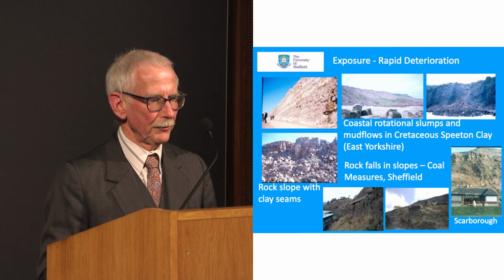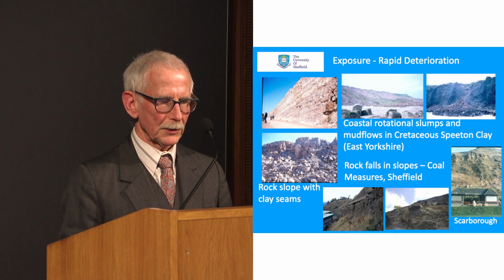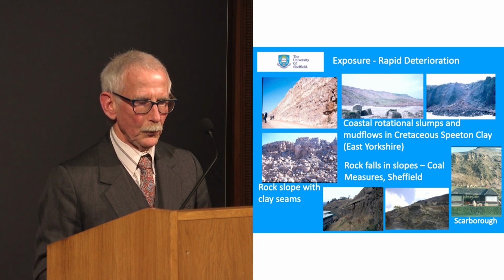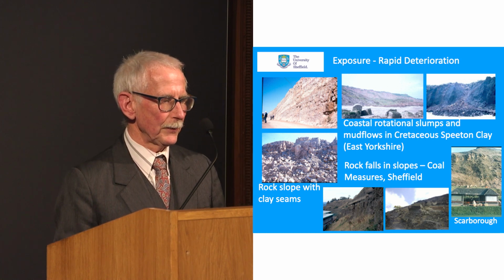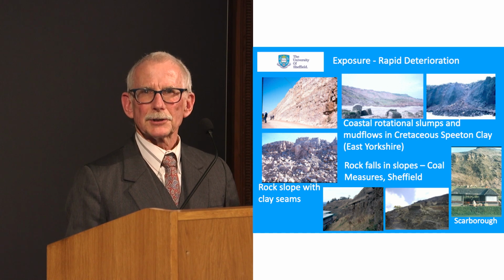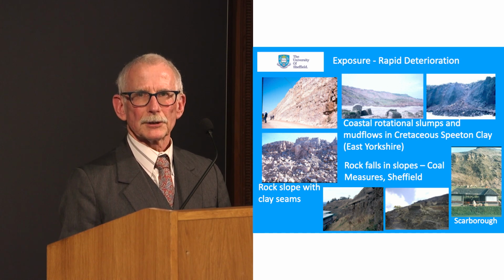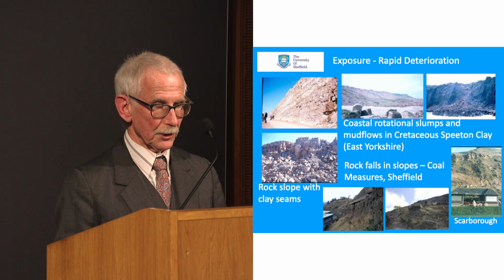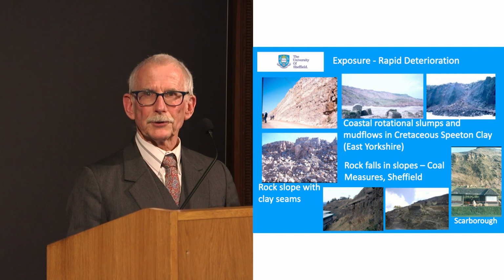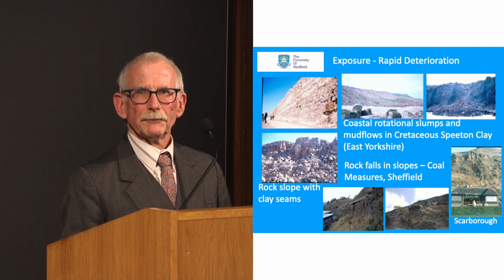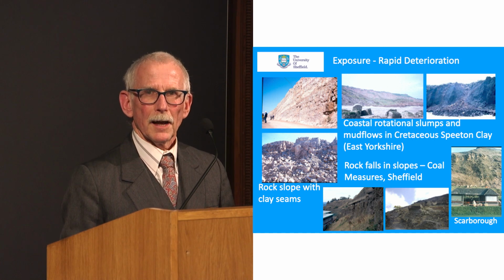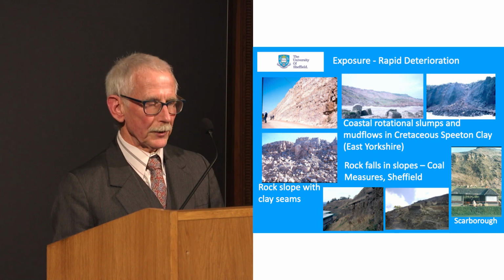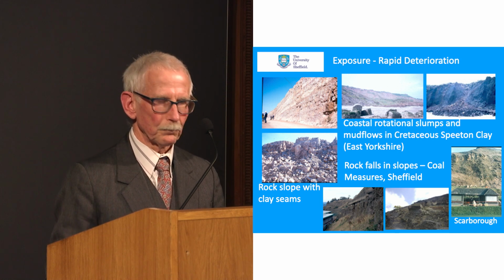Mud rocks occur in engineering because they're the in situ material in slopes and other situations, and may suffer various forms of instability in slopes. Weaker mudstones erode more rapidly than interbedded sandstone or limestone beds, as seen in the slides at the bottom of the slide, and also the bottom right, which are examples from Sheffield and Scarborough. In the case of the Scarborough one, in the bottom right corner, lumps of limestone have fallen off that cliff and hit the shelter that you see because of the weathering of Oxford clay, which lies underneath it.